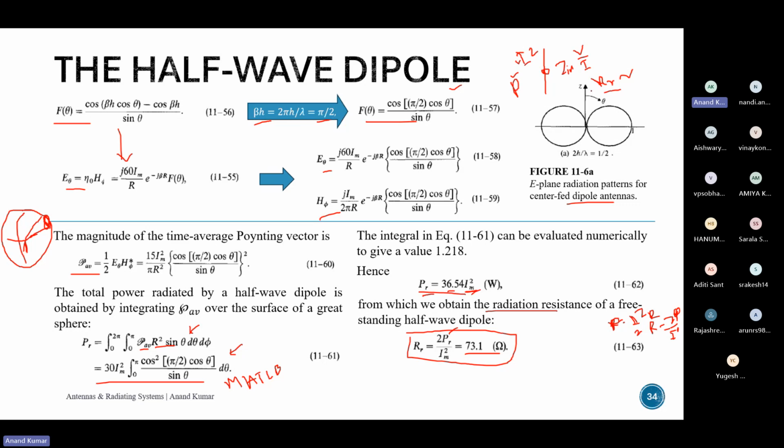And input impedance is the ratio of voltage to current at the port. This is used when you have to match the antenna to the rest of the circuit. So if there is an impedance mismatch, you have to make sure that you put in a matching circuit. I hope that made sense, Hanuman. Do you have any follow-up questions?